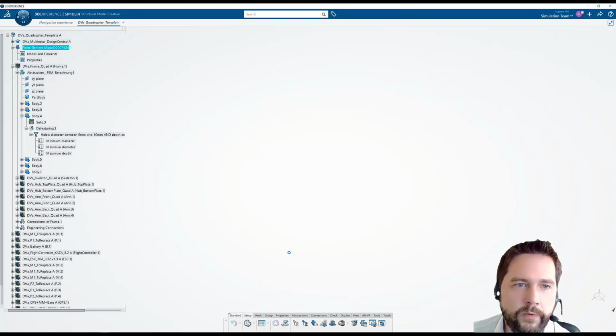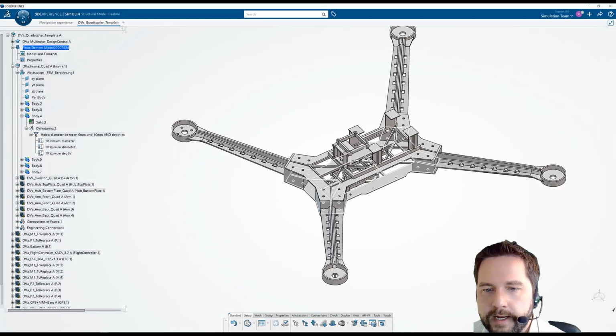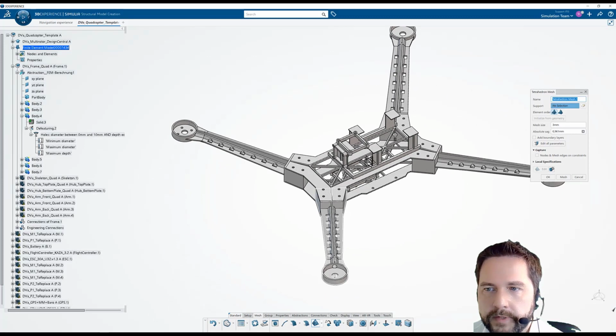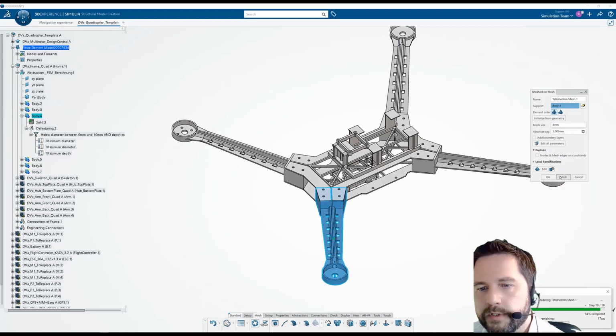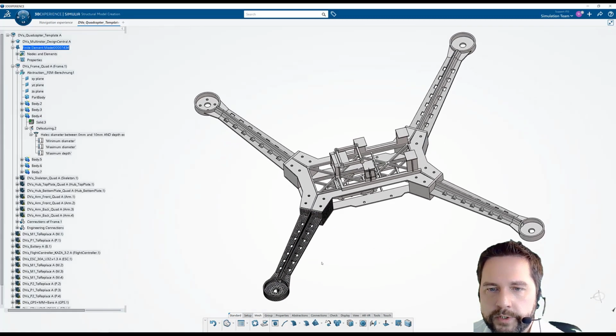We're showing again the parts. And now we can, for instance, put a mesh inside one part and only the abstraction shape will be selected. As you can see, we can select something like 3 millimeters for the mesh. And you will see we have a mesh without the holes. So the defeatured geometry is meshed.